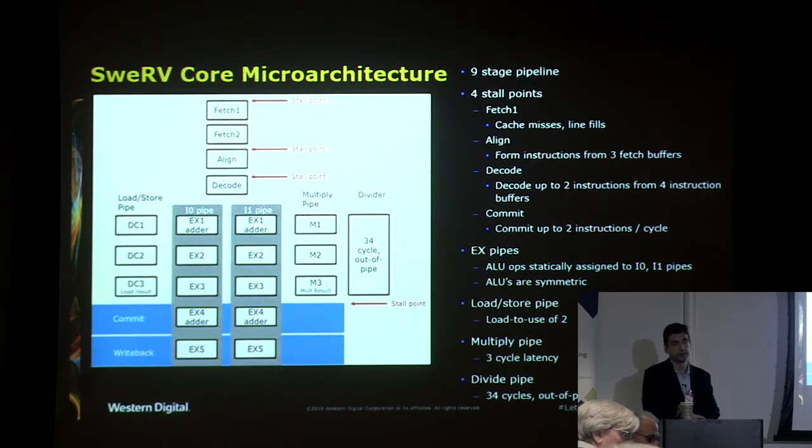Absolutely. It may make sense to go superscalar for a central processor in a large system, but not necessarily. Even today the 8051 is still the dominant processor for embedded firmware. One of the reasons is it's very simple, and because it's simple, its interrupt latency is deterministic and well understood. So this is a very real issue.